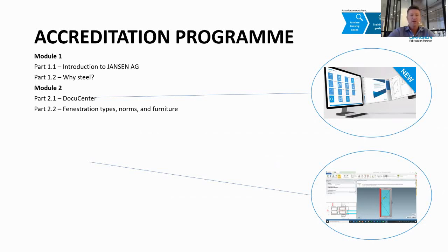Just to give you some background, in order to communicate with architects and with metal workers, it is best to have a shared language. So what the Europeans have done over many decades, in fact around the world, what the world has done through ISO standards and other norms and codes, they've developed norms and ways of illustrating, whether it's icons or typology or symbols, which indicate what you're looking at when you look at a drawing. So you'll see on some of the window and door drawings, there's little annotations that are either hatched or in a triangular shape, and that indicates where the doors open: inward opening left, or inward opening right, or outward opening left, and so on.